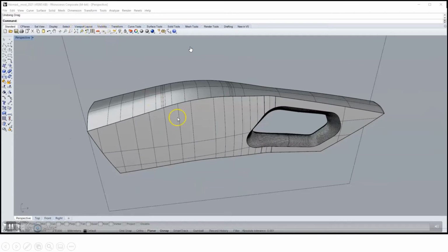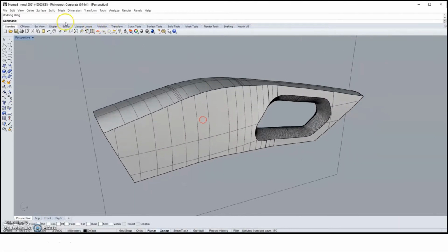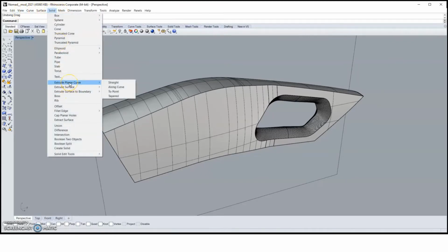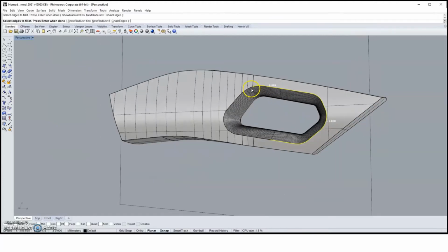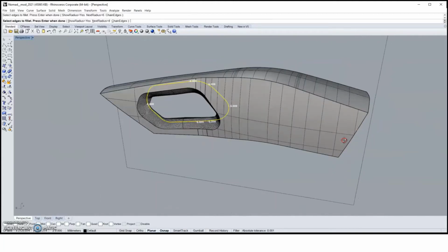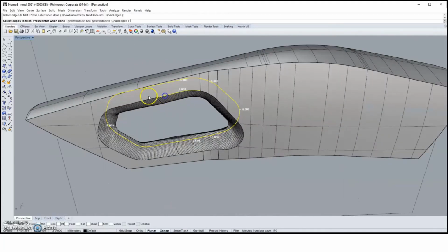And here we are going to carry on to build more radiuses, because in a product like that, normally a sharp edge with the surfaces wouldn't work very well. It would not be very ergonomic and won't be very nice to hold at all. So we are building, using the edges, defining the edges and building radiuses around that, so it creates a smoother curved surface there.